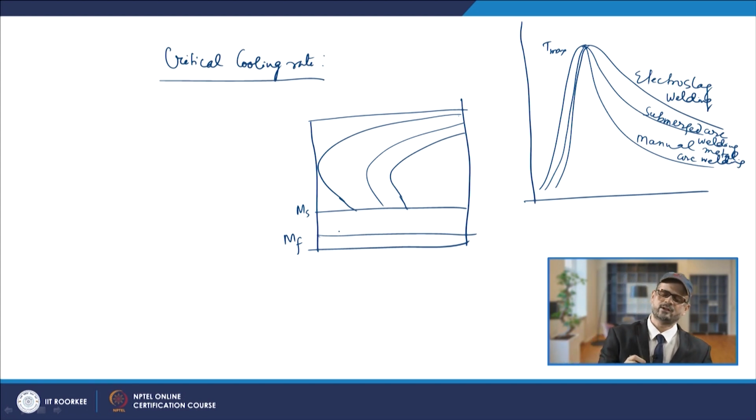So basically you will have some pearlitic transformation. So what we do in such materials is try to increase the hardenability by the use of alloying elements. These alloying elements will shift the TTT curves towards the right. So many a times we use alloying elements in the filler material. Its job will be, because you have the transformation in a particular zone, that it undergoes the transformation.